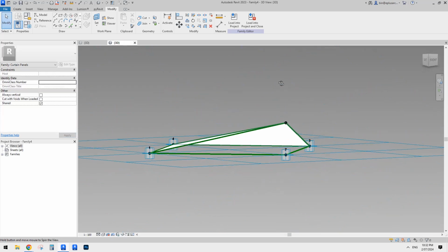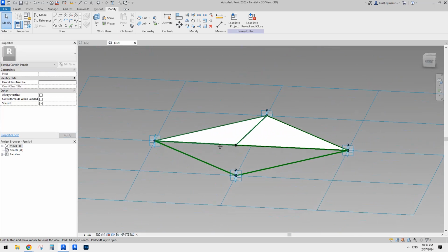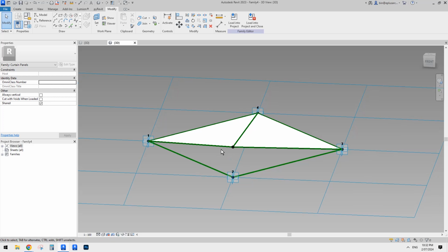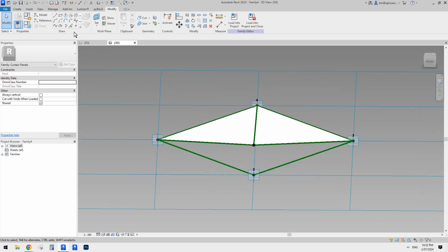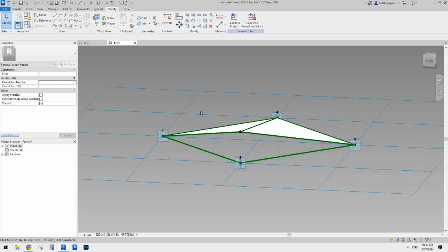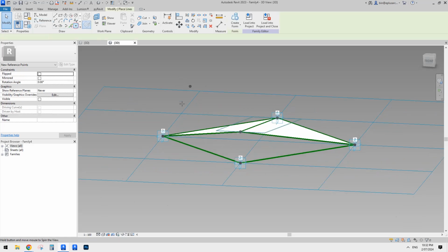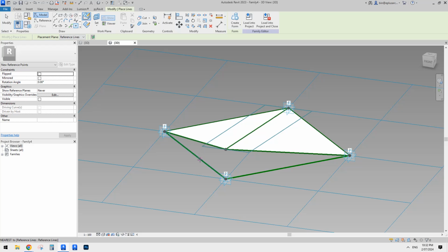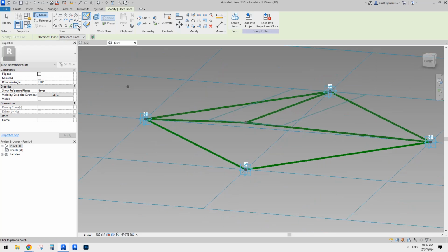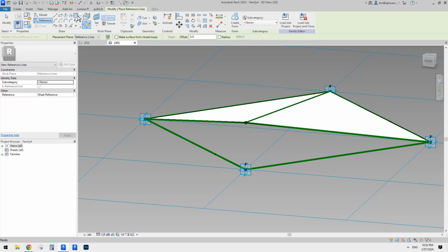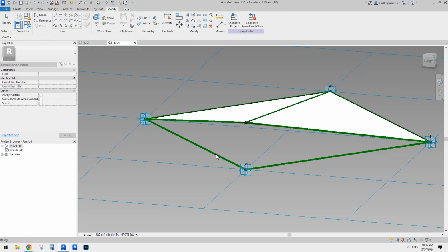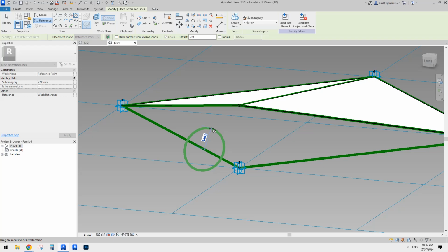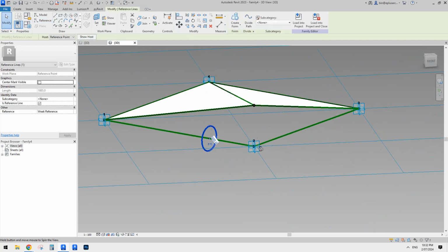So I think if we do not worry too much about the overlapping or the actual element, we can just quickly place a point, use draw on face. So I would do this, point, draw on face, place onto this point, and we can just create a circle, use a reference circle, draw on world plane, set world plane, pick this, and we can just create, not sure about the size, but let's make it a 300 radius, so 600 diameter.